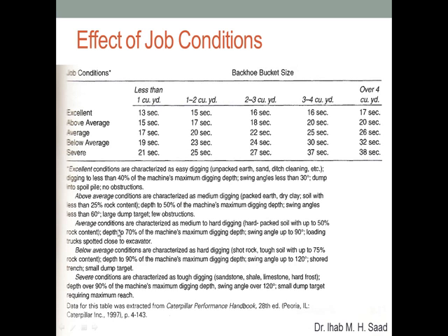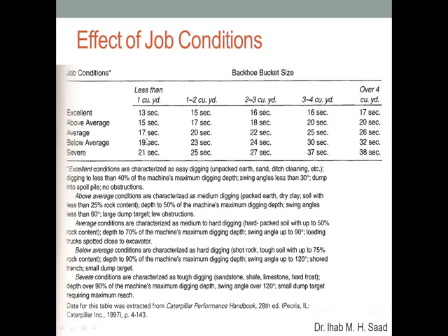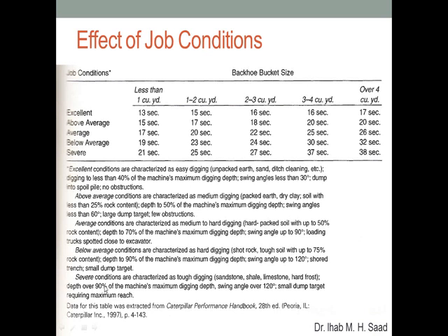And so on. If we keep going down, we're going to see that the average conditions, for example, are more hard-packed soil, depth even more, 70%, and the angle of swing up to 90 degrees, and loading into trucks. So you have to spot and you have to adjust, you have to maneuver, which again is going to slow down the operation. Up to when we reach the severe conditions, we have digging through tough and hard soil, depth over 90% of the maximum digging depth, so we are almost extended to the maximum, and a swing angle of over 120 degrees. So basically we are moving more than 90 degrees. It's basically almost facing backward.